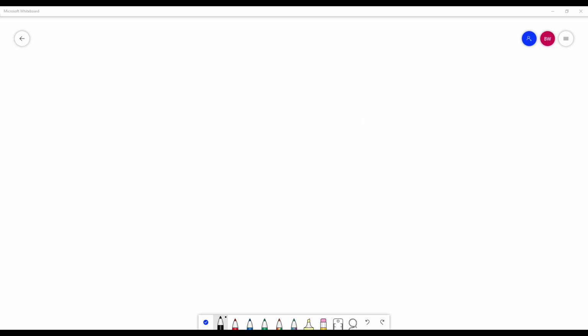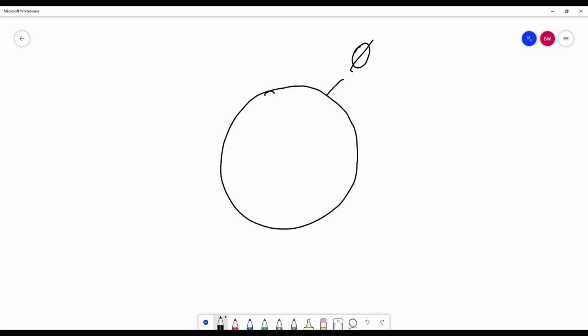All right, so let's work through circular interpolation. Okay, so let's say we have to cut around a circle right here, and the circle diameter is 2 inches. Okay, let's say our 0, 0 is in the middle. Okay, and we want to work around the workpiece counterclockwise. Okay, something like that. All right, so let's program this.